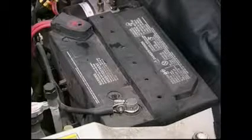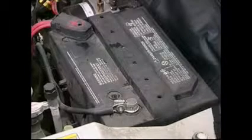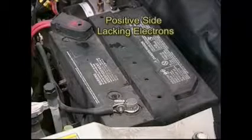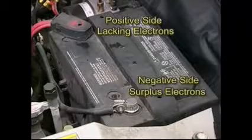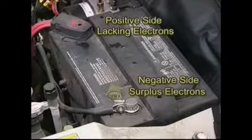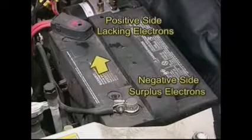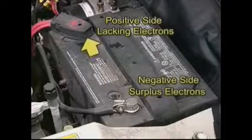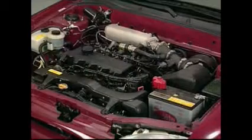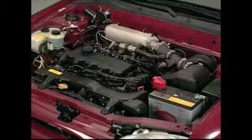An electrical power source provides for a more positive charge to allow for a continuous flow of electricity. It supplies an excess of free electrons in one place and a lack of electrons in another. In a battery, a chemical reaction causes a lack of electrons at the positive terminal and an excess of electrons at the negative terminal. This electrical imbalance causes the electrons to move out of the negative terminal and seek a path to the positive terminal to get to the protons of the positively charged atoms. The paths that the electrons travel through are the wires that comprise the individual circuits of the automobile wiring harness.